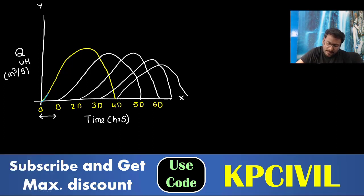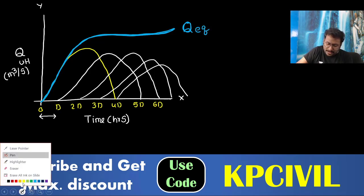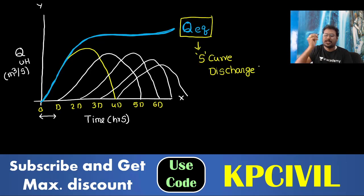you can get a peak discharge value which continues for a long time. If you add all the values of the delayed unit hydrographs, you will get the equilibrium discharge QEQ. This QEQ equilibrium discharge is called the S curve equilibrium discharge, the S hydrograph discharge, QEQ.